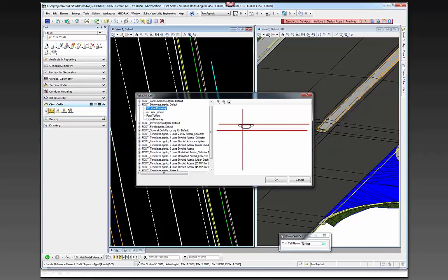What we've done is we've gone ahead and made these 3D so that if you have a profile on these 2 lines, it will create all of the reference lines, similar to what you see in the Bentley videos. And then the 3D urban driveway is that too. If you have a back of sidewalk profile and a profile on your edge of pavement, then this left line is basically all you need to identify, and it will project the slopes according to the standards for each of these driveway elements, which is what I'm going to attempt to place at this point.